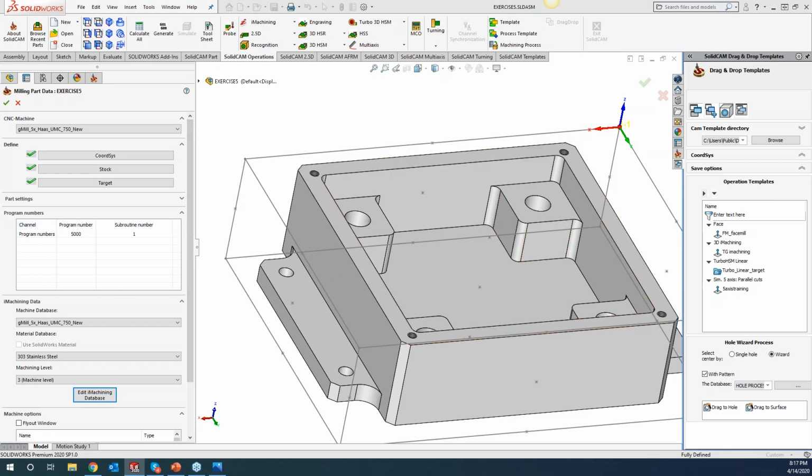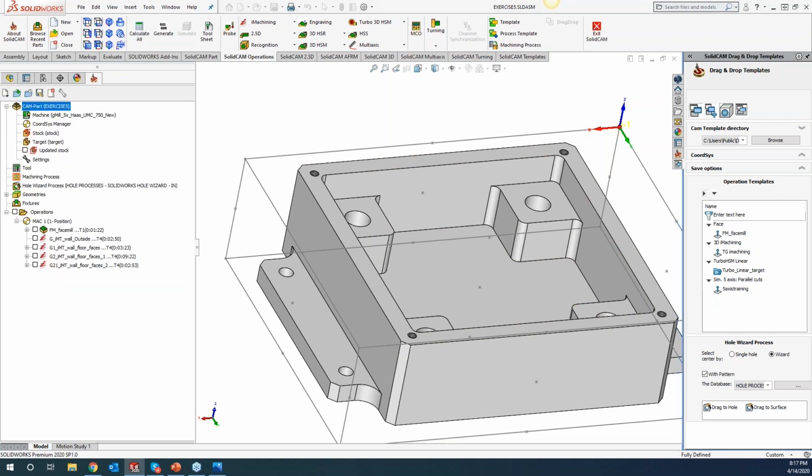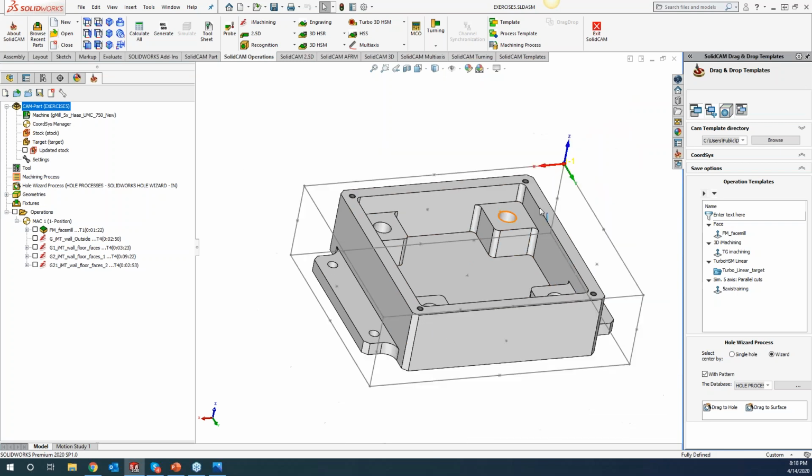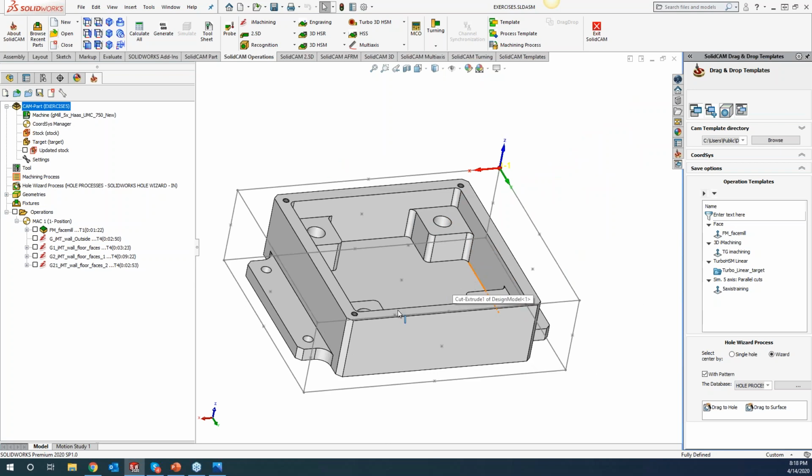All right. Now, another one that I would like to show you guys is we all often get the question, iMachining is very long in G-code, which it is because we're constantly monitoring the angle of engagement, and it's doing a lot of arc moves in there. Well, we can get that changed by decreasing the arc fitting tolerance.